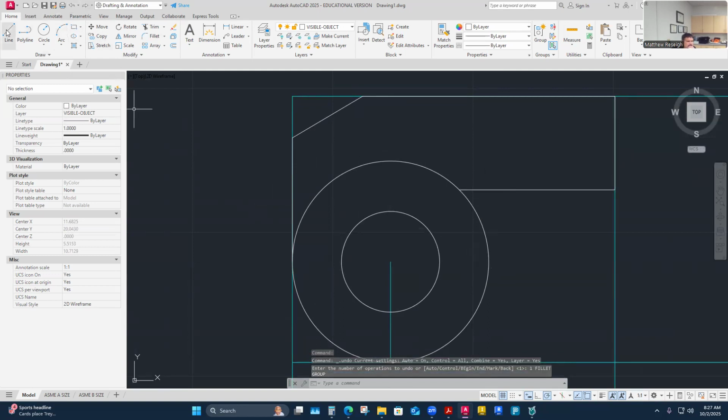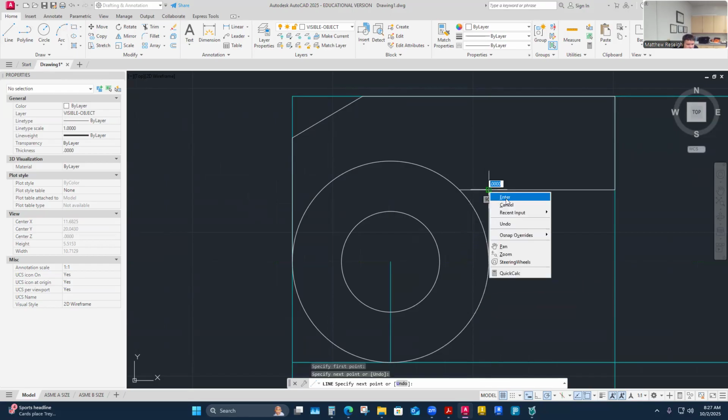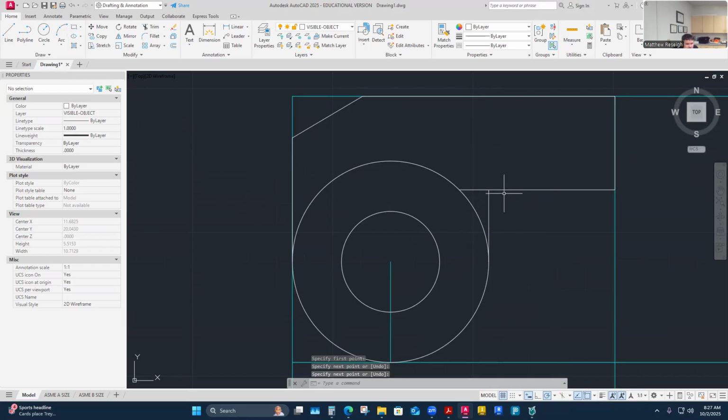Definitely. So I almost need to draw a line like this, and I can just use the quadrant as tangent here, because that's where it's going to transition from this radius to where I go back like this. And I should be able to fillet it now and have a totally different flow to the fillet, right? So I can just press enter, because I don't even have to do anything. I've already entered that it's a 1/2 inch fillet. But that's not going to work either. It's going to do something weird.